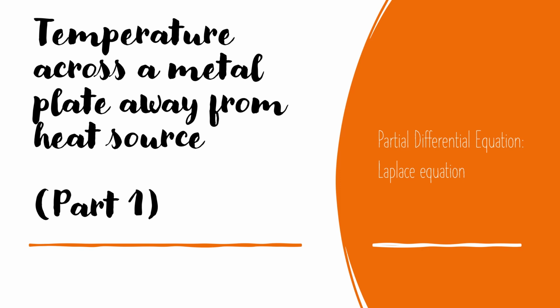And we are going to look at a case in the middle of the plate where there is no heat source. When there is no heat source, that is when you can apply this Laplace equation. If you are talking about a location with a heat source or any other sources, then you have to use another kind of equation, which is the Poisson equation. But let us keep that for the next few classes, and now we will concentrate on the situation where you have a metal plate without a heat source in the middle.